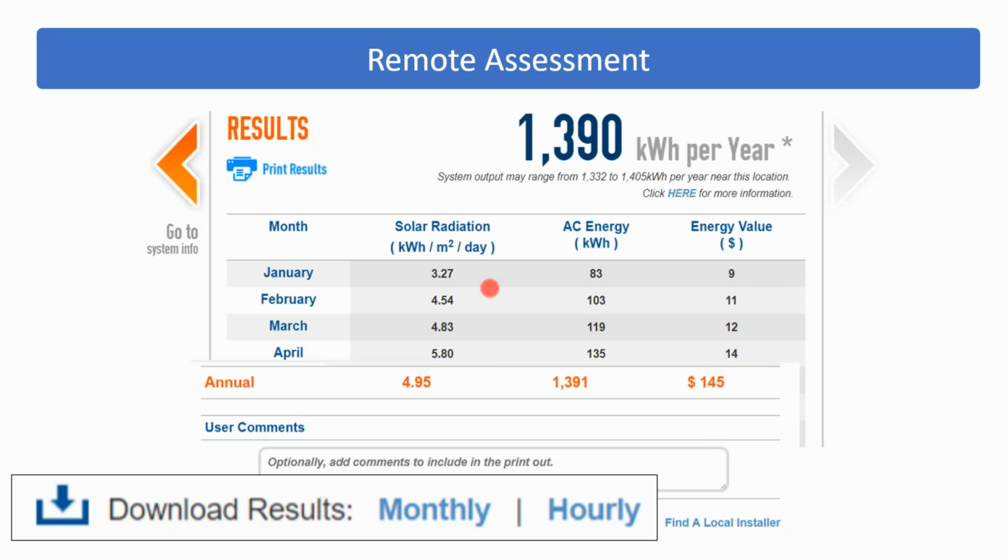And some solar installers take that and say, well, there's really only a 4-hour window when the solar array produces all of its electricity. And that's not really the case. It's more of an average from the morning into the evening that gets compressed when they're talking specifically about sun hours, which is really just a mathematical tool that the industry uses to perform some mental math.